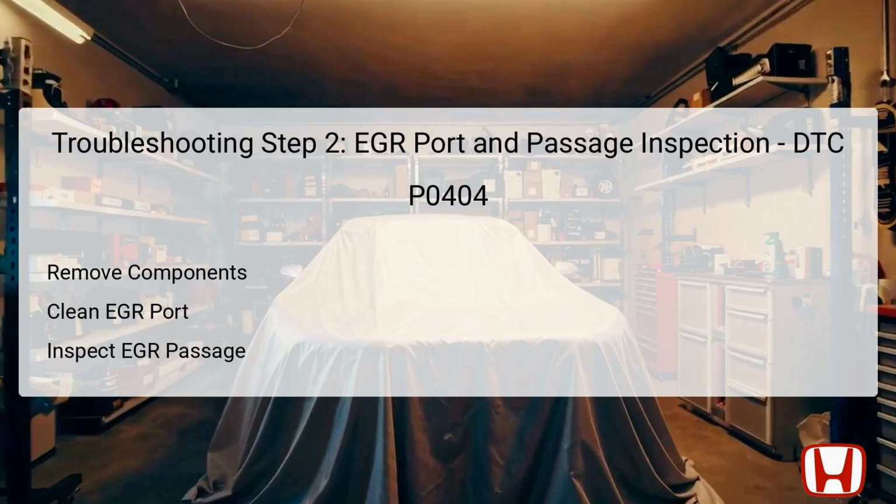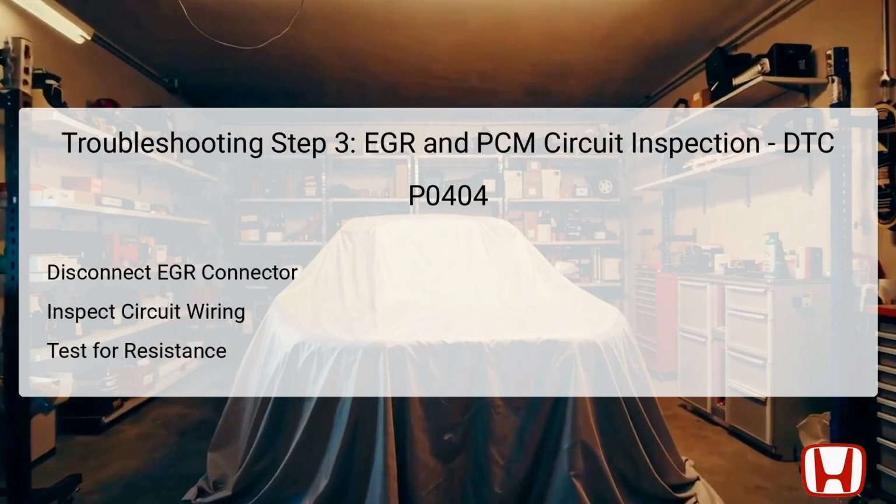After cleaning, you will then need to perform the HDS EGR test, checking to see if the results are normal to confirm that the issue has been resolved. The third troubleshooting step requires inspecting the EGR and PCM circuits. Start by disconnecting the EGR valve connector as well as the PCM connector. This disconnection will allow for a thorough examination of the associated wiring and circuits.